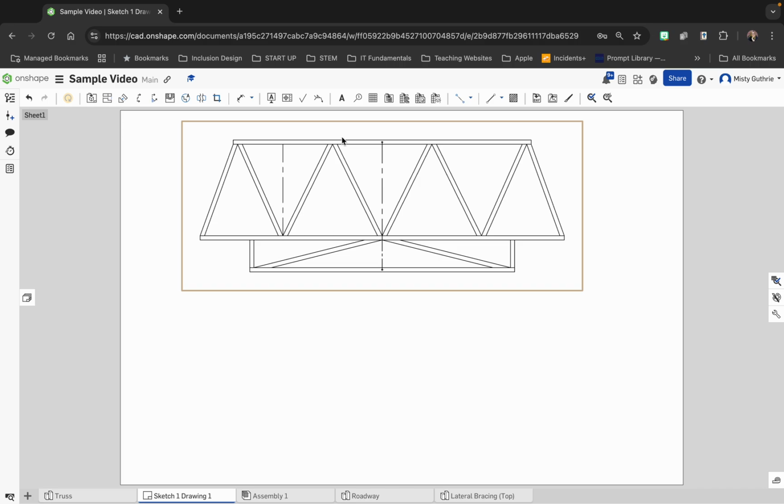If you made a lot of crossovers where the lines cross everywhere, you can clean those up using your trim tool. I'm not in the sketch right now, but the trim tool looks like scissors, and when you click on things, you can easily remove them. It's also good for removing construction lines.